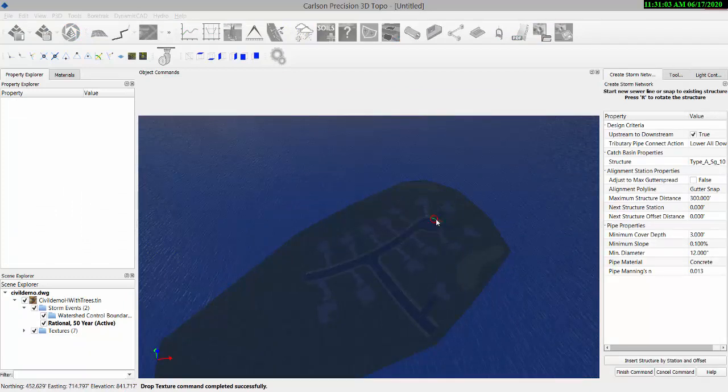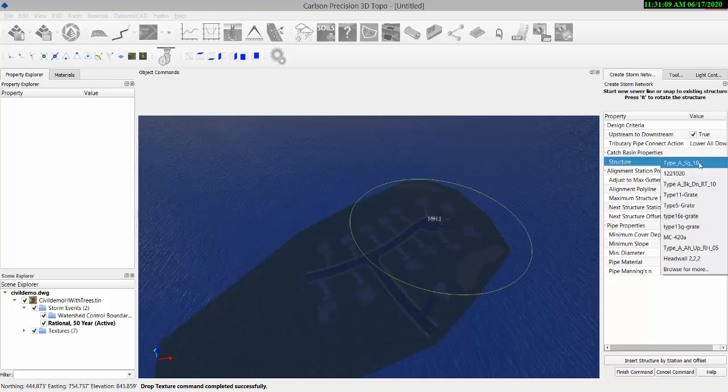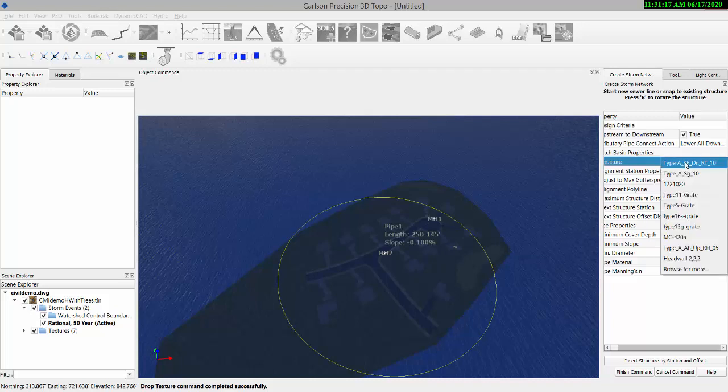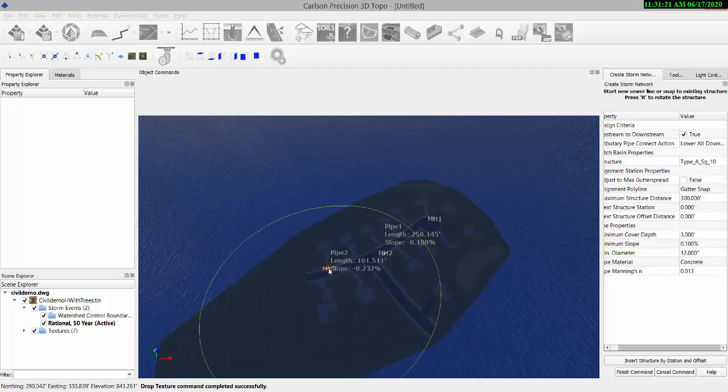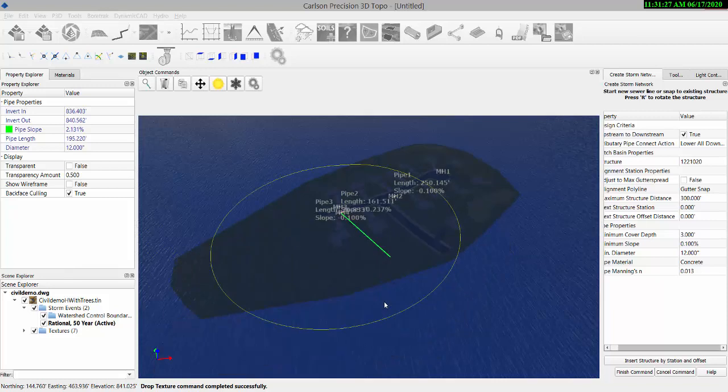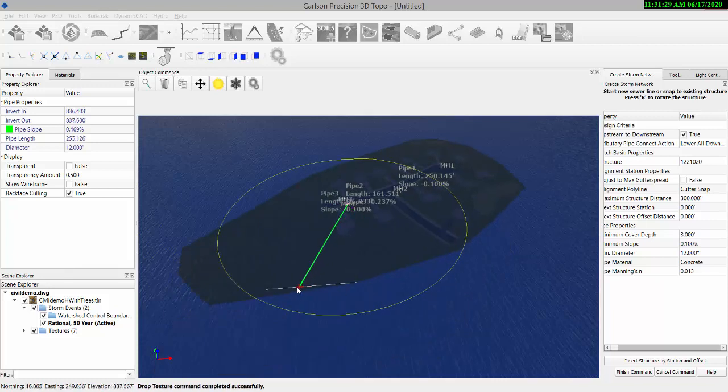So we'll go from this low point in the curb, we'll switch over to a downhill facing manhole lid in a 10-foot curb inlet. We'll use the 10-foot curb inlet here at that low point, and then we'll finish up with a headwall along this right there.